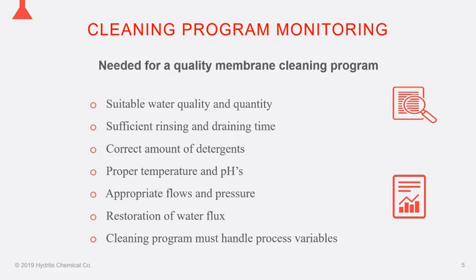You've probably been to lots of facilities where, if the water quality isn't there, especially on the silica side, which we'll get into a little bit later, it can impact the way the system cleans, as well as the quantity. If you have systems that don't have enough water supply, especially when doing rinses, you're stopping and starting, and that can impact number 2 on the line, which is, of course, rinse times. We discussed that earlier, very, very important to a CIP program.